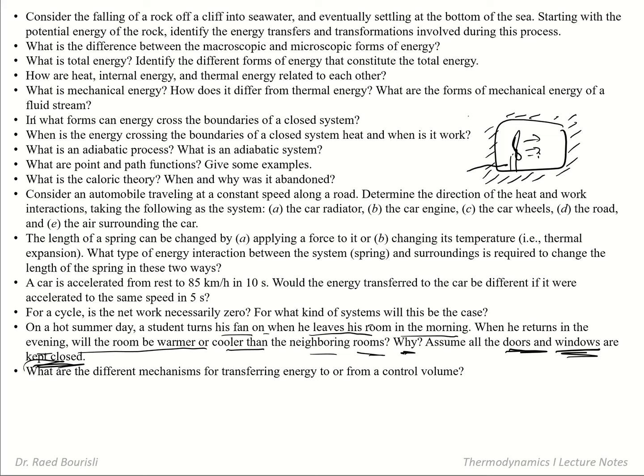Well insulated does not mean that Q here is 0, and it does not mean that there is no electric power coming in. This gets some electric power and it moves air around. If you look at the change in the energy, there is no heat, but there is work. The change in energy will be translated not into kinetic energy and potential energy, because this is stationary, but into internal energy. So I'm adding work, it will increase, no matter what.